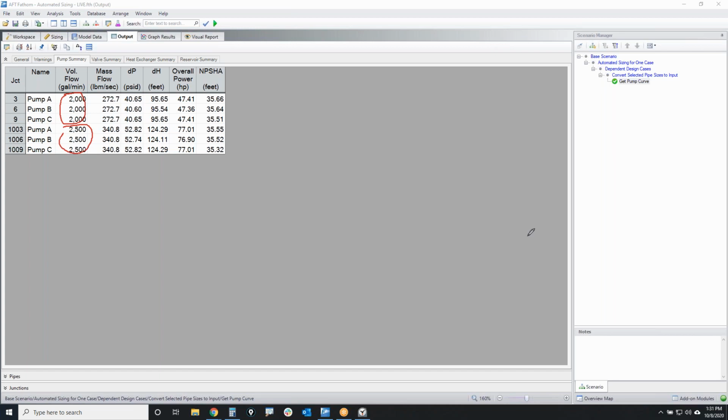Obviously when you size your pumps, you don't want to pick the lower option, because then your pumps are going to be undersized for the 35% higher flow case. So we need to go with the higher flow pumps, and we need to use the operating point of 125 feet. So now I'm going to click on the pump with the spark on it.